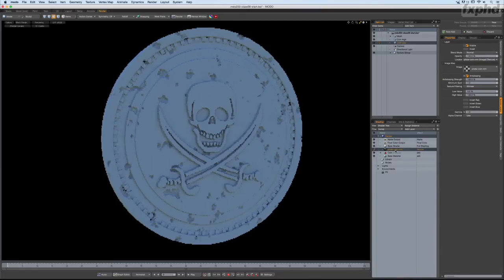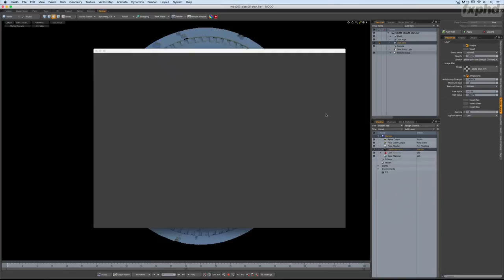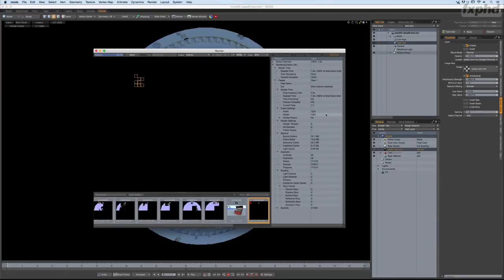So once again, we'll right click, bake from object to texture. We'll leave the distance at 0 and hit the OK button, and now we are off to the races. And we are. Now, if you check it out, look at all that lovely etched detail coming from our procedural texture being preserved inside the normal map, and we're going to be able to apply this back onto our geometry inside the scene. However, if you look critically at what is being captured here, we're not capturing everything.